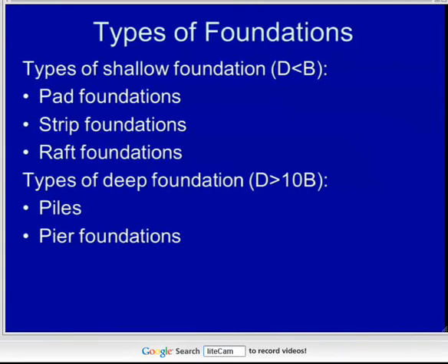Okay, so we covered that last time. This is just a summary. We said for shallow foundations, we've got pads, which are square footings founded 1 metre, maybe 2 metres below ground level, with a similar aspect ratio in the two directions, often used to support individual columns. We've got strip foundations, which are long in one dimension, used to support load-bearing walls, and rafts to support the whole structure. And what we're going to look at is a mode of analysis that covers all that category.